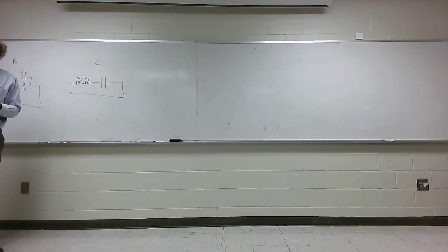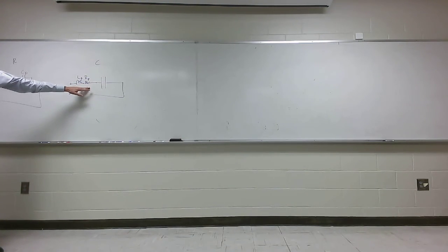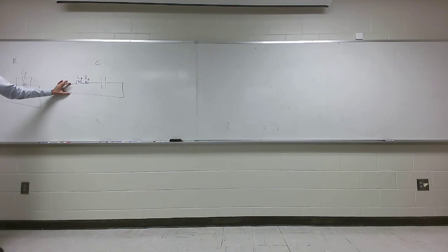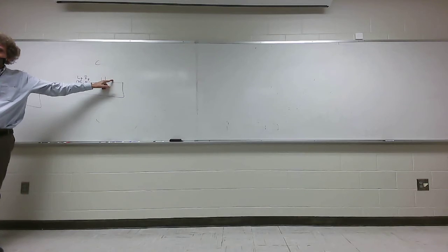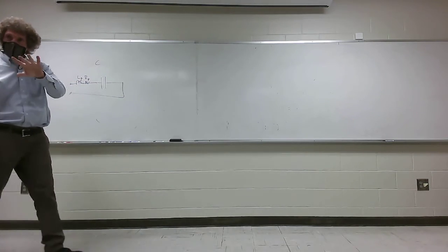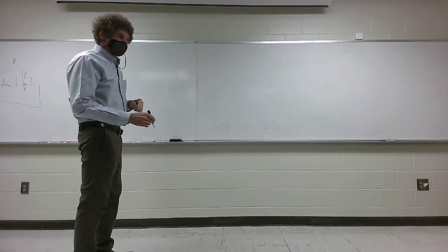Do y'all remember that? The capacitance is given. And the reason is, if you look here, isn't the impedance of this system between these two terminals when the frequency is 0, isn't it infinite? So there is no leakage resistance. With an electrolytic, they put a leakage resistance here. And that model is a little more complicated, and that's only for electrolytics, really.